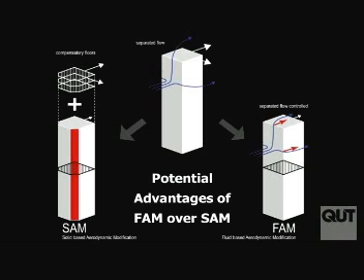Okay, so I want to switch gears now and talk about fluid aerodynamic modification. So that's not changing the shape of the structure, not adding to the stiffness of the structure, not adding to the damping of the structure, but just changing the flow, manipulating the flow around the structure. And of course, all of the things about changing the shape or adding stiffness or adding damping all take up or take away internal volume of the structure. If I cut corners on the structure, then I'm going to lose rentable space. If I add dampers, if I add stiffness, more massive structure, then I'm taking away from rentable space.